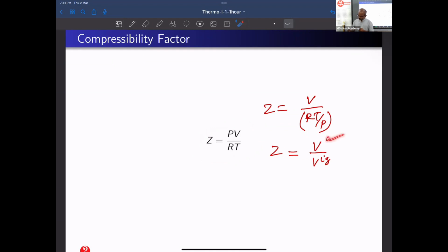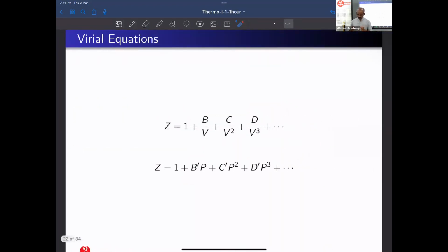The actual volume and the volume estimated from the ideal gas equation may not be equal. They will be equal whenever the pressure is low and temperature is higher in comparison to their critical pressure and critical temperature. Z is equal to 1 for ideal gas. The value can be lesser than 1 or greater than 1 as well. This indicates the deviation from ideal gas behavior.